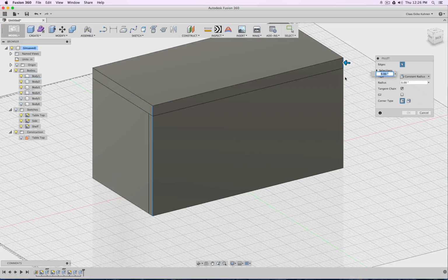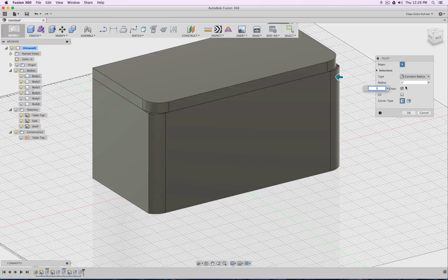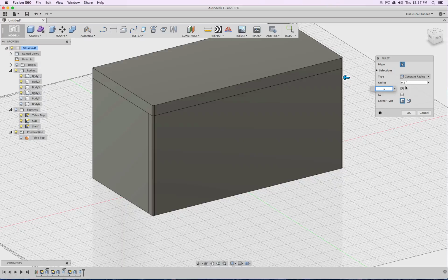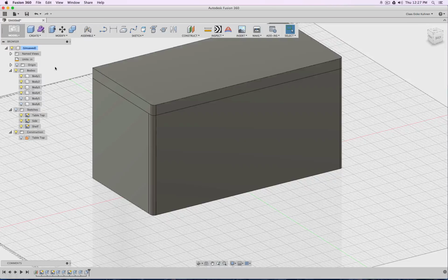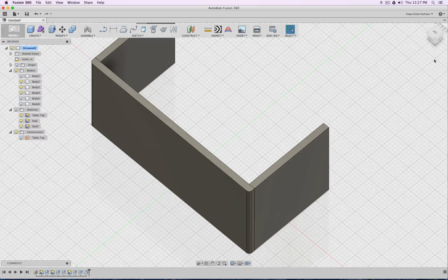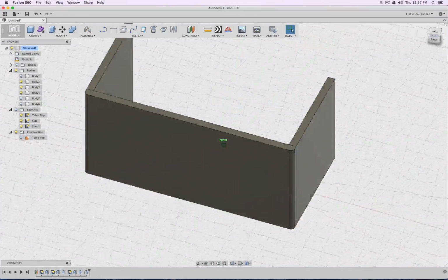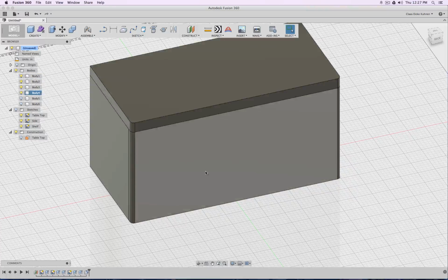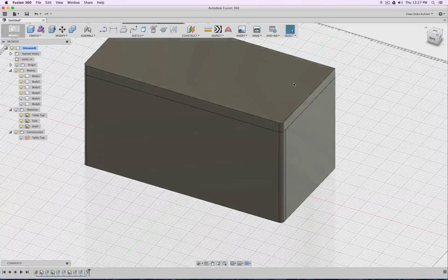You see, I can round corners of multiple objects, and maybe 0.5. Ooh, 0.5. With 1. Yeah, let's go with 1. Okay, good. So let's hide the top and let's take a look. And there we see what we have. Yeah, that's kind of like what I was looking for. So for example, if you come from the front, this is a little bit rounded, looks nicer because these edges are very prone to chip off because somebody banged something against it.